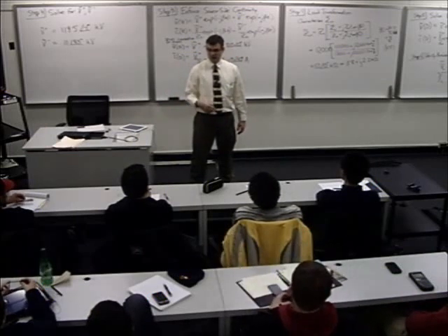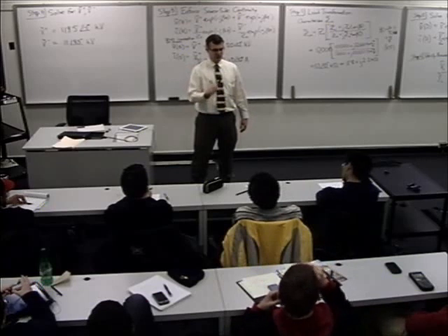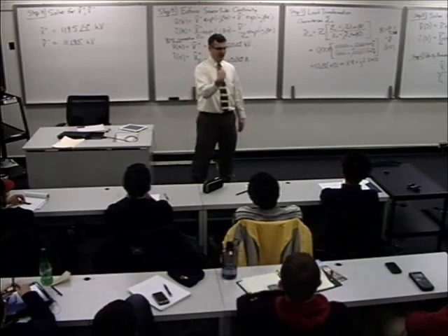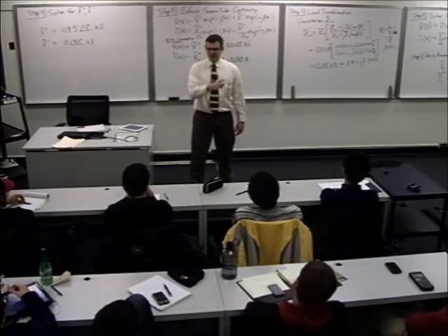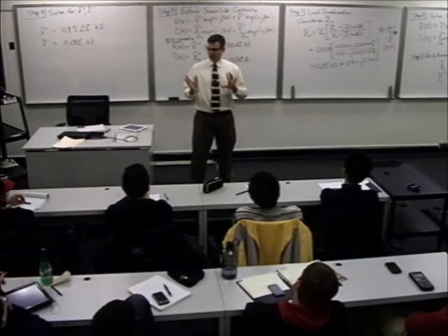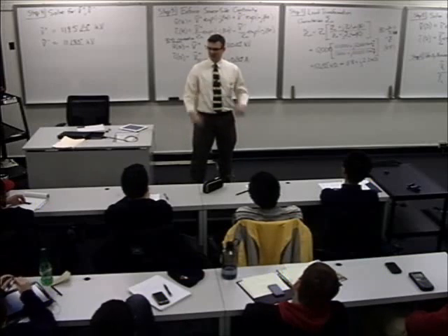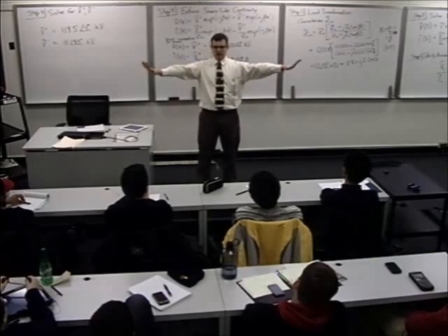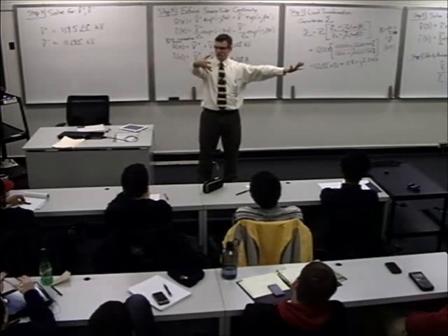You have to take the real part because you don't care about the VARs on the line, the oscillating power to and from the source. And you have to use the 1/2 because we're dealing with sinusoids in terms of real-time averaged power. If you average sinusoidal power, it's always 1/2 times the peak amplitudes in that expression. So we know from basic circuit theory how to calculate the real power leaving the source.